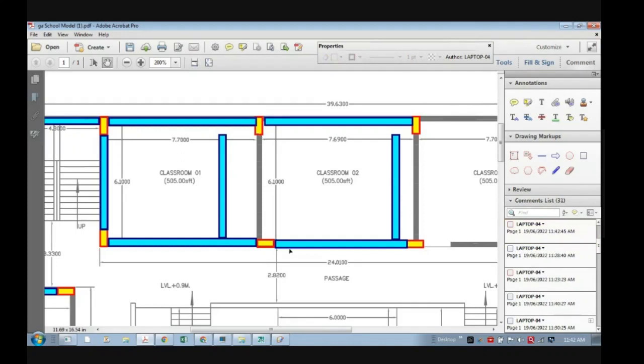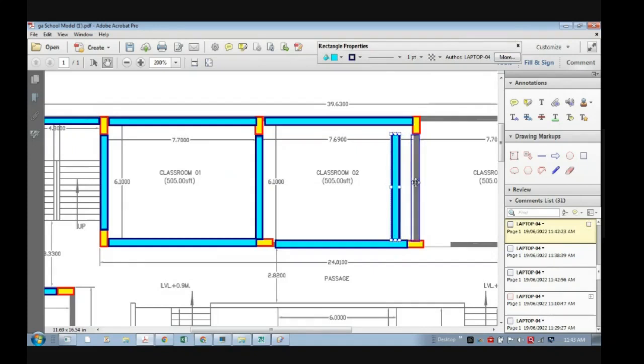If you take it at the center, then you need to shift this also to the left so that you can provide the beam exactly flushing the column. So this is also one of the choices. So what do you think, which one is better in your opinion? This one, sir. Keeping at the center, this one? Yes. So this one looks okay.